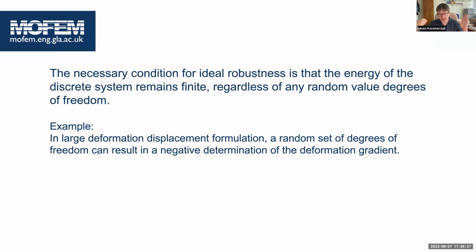So you have a soft body which impacts the wall, and in the moment when you do a large step, and then when you enforce the constraints from the impact, from the contact, then you're generating inverted elements. Your system blows up. You have to reduce the step and try again, reduce the step again, and then at the end when you want to have high velocity impacts for large strains, the only way is to do an explicit method,